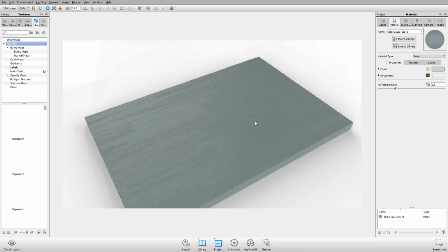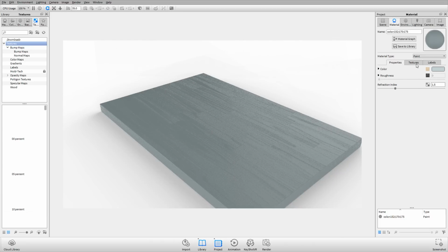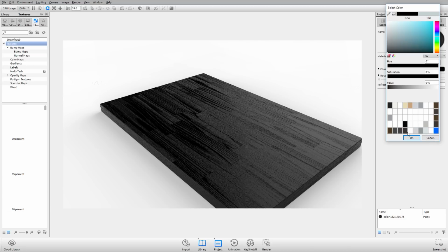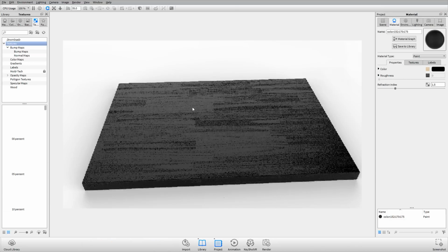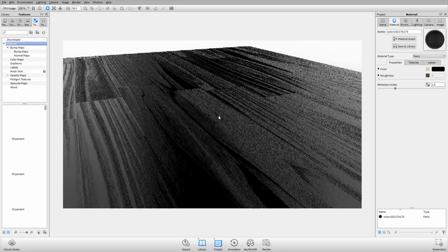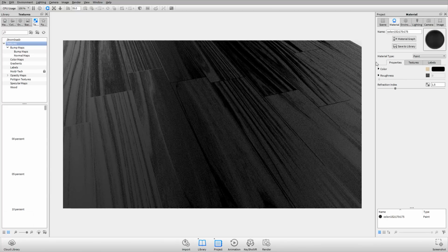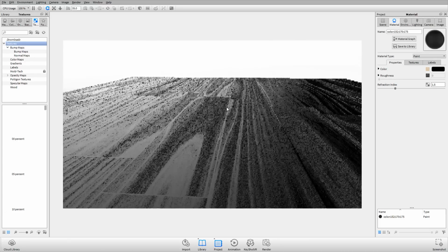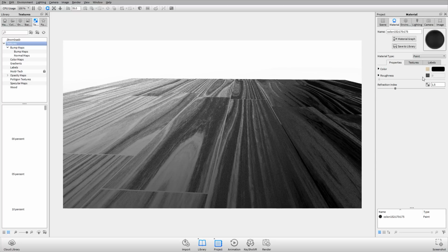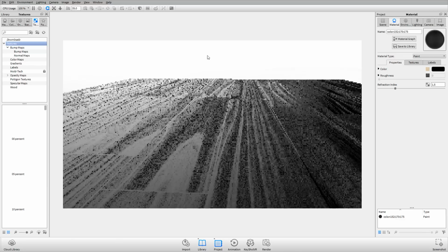And so what this image is doing, and so we see this better with some contrast, I'll make this paint black. What we're doing here is we're actually determining surface roughness. And again, we got a lot of questions about wood. This is one of the top tricks for working with your wood material. Use roughness textures. Because what we're saying is anywhere that texture is black, it's going to be smooth or shiny. Anywhere it's white, it's going to be slightly rough.